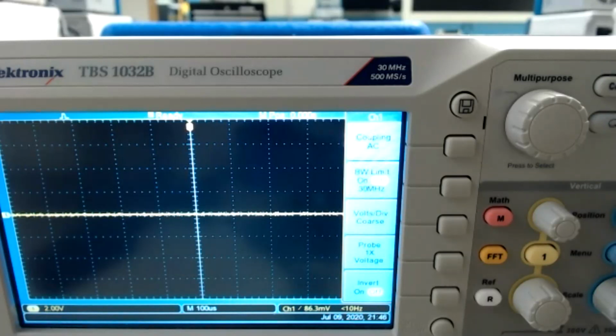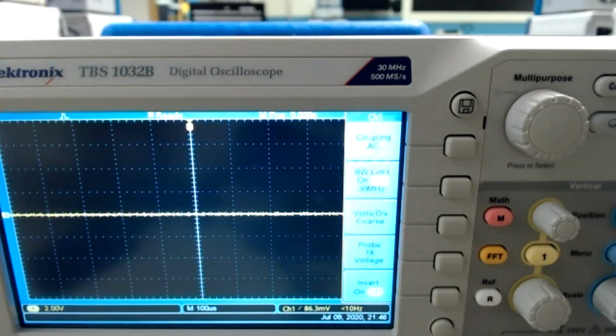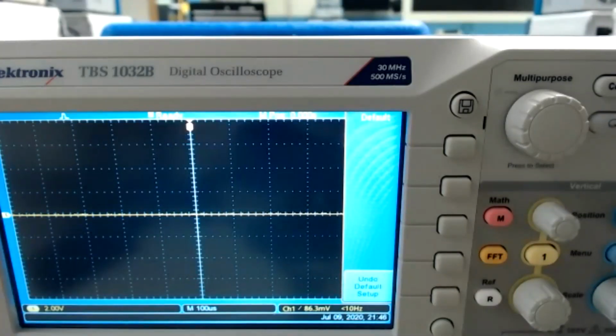So we're gonna start with the procedure. We're gonna turn on the oscilloscope. If you see my finger over here, the switch is over here. It's already on. And number two, a previous configuration may be loaded. Load its default setup by pressing the default setup button. You don't see it right there because if I move the oscilloscope, I'm gonna lose the focus on the bottom of the screen, and I don't wanna do that. So I'm just gonna press the default setup. And here on the bottom left corner, you can see default setup recall. So that's step two.